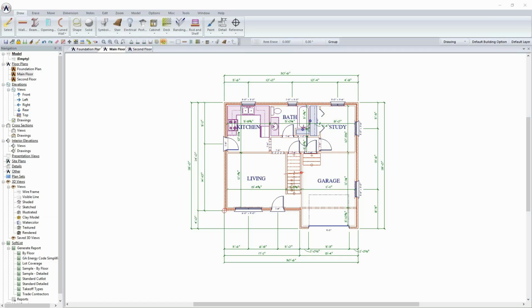However, one of the things you're going to need to do is treat your drawing like a database. And that's where we as designers, architects, and builders sometimes get ourselves into trouble, because we shortcut the drawing. Something simple such as these cabinets that you see on my floor plan: if you draw those in with lines, you should expect nothing back on the bill of materials because, after all, a line does not represent a cabinet. So it really comes down to accuracy of drawings in order to get an accurate bill of materials.